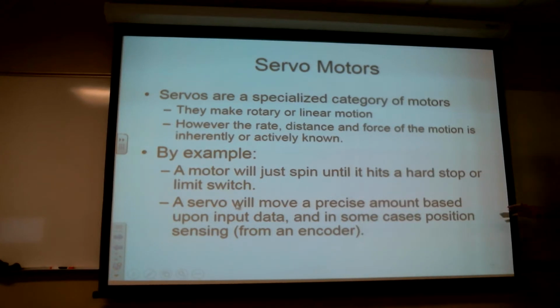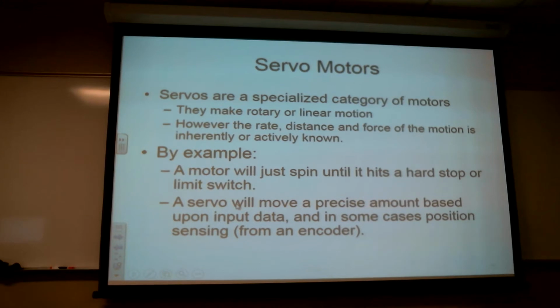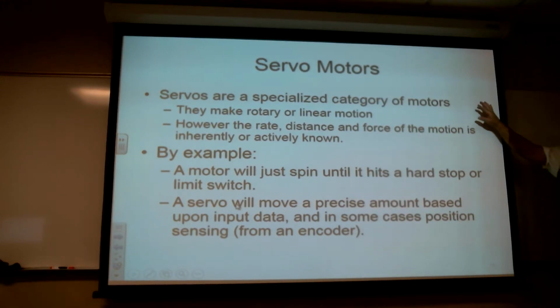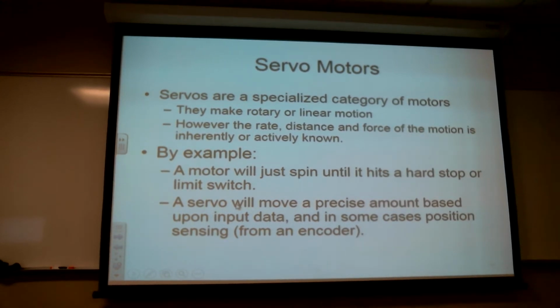In a true stepper motor, it's just going whatever direction in a finite amount, but it doesn't really know where it's at. A true servo motor has some type of an encoder in there that also tells it where it's at. This guy, the motor doesn't know, but the little limit switches tell when it's at either end. Thunk, thunk. Anywhere in between, it doesn't know where it's at. A common strategy for many of these servo type devices, instead of using an encoder, is this: when you first turn it on, it has no idea where it's at.